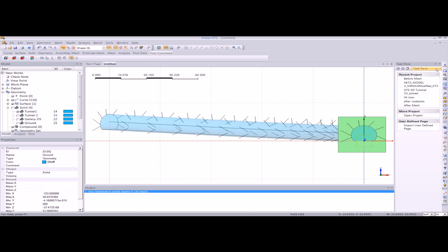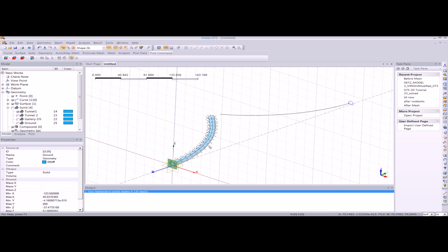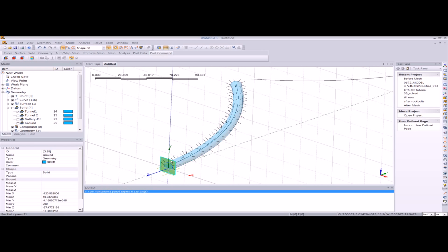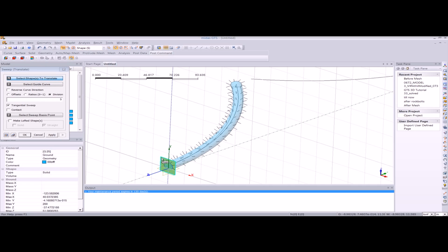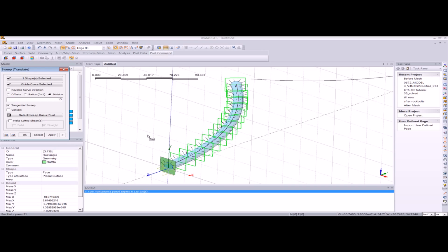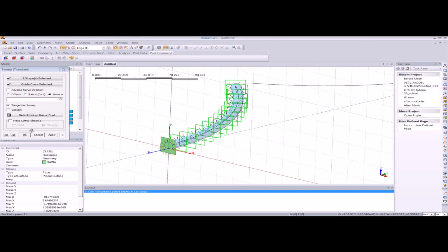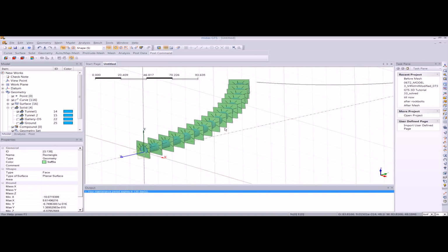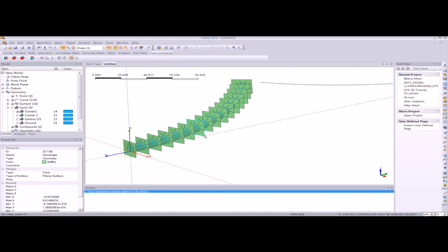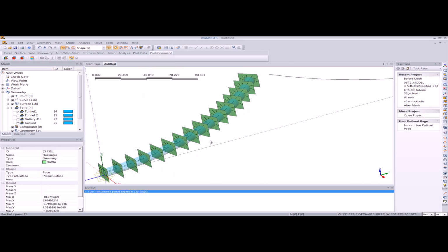And now I'm gonna translate the surface to the locations of several excavation stages of the tunnel. So I'm gonna sweep translate this rectangular shape along the guide curve which we used for the creation of the tunnel, and this is how they will be transformed. And once I click on OK, I have several rectangular shapes that I'll use to divide the solid depending on the excavation process.